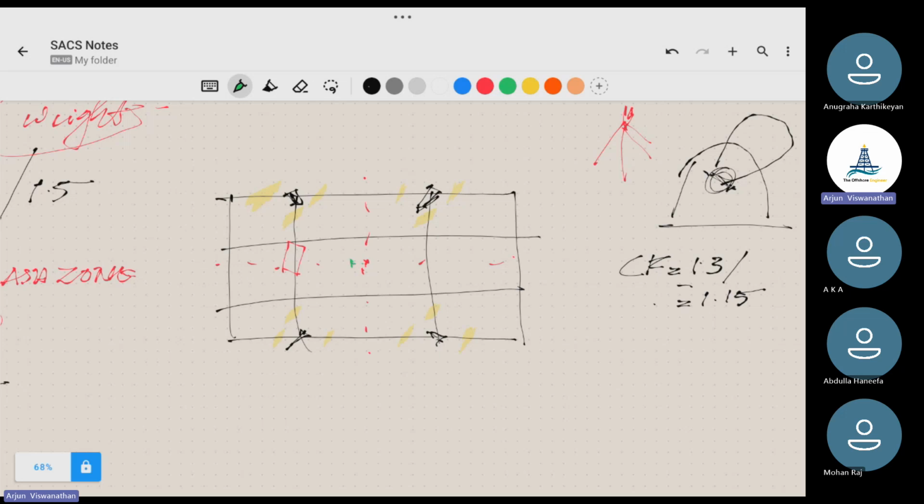Then we connect the slings to that hook point. So this COG location matters a lot. If our hook point is not at the COG, the structure will not stay flat, and we always try to make sure our structure stays flat, unless otherwise intended. Sometimes they will exactly tell us they want to lift the structure in an inclined position. But in an ideal case, we will make sure our structure is horizontally level.